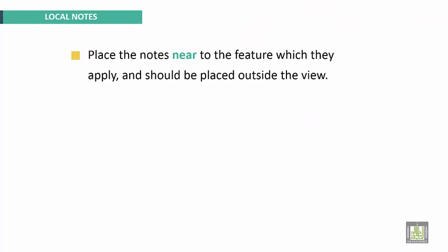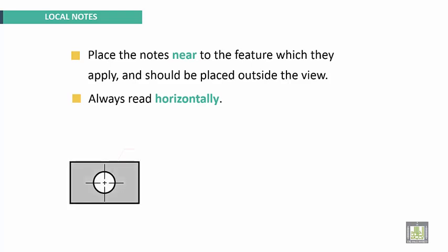Local notes. Place the notes near to the feature which they apply to, and they should be placed outside the view. Always read it horizontally. One example here, this is local note 10 drill, and put here a space of about 10 millimeters.